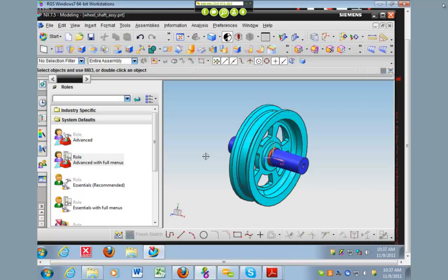The last one is what's called a 1D rigid. It's a lot like what we used in HyperMesh for connecting constraints to the rest of the part. In NX Nastran, it's commonly used for bolts or pins or a centralized load, much like HyperMesh. Those three are really the three ways to connect things together. Generally, you'll be using gluing or the 1D rigids. Does anybody have any questions about that? Cool. Yeah, Eric will show you a little bit more about those.